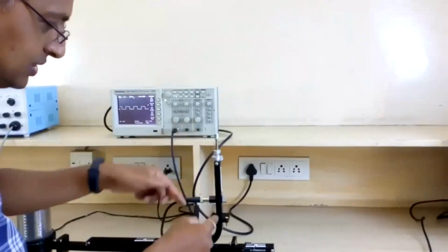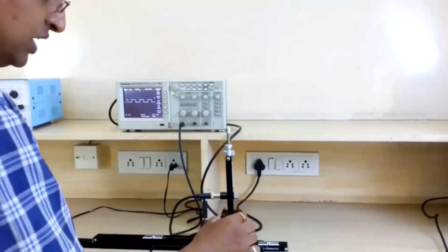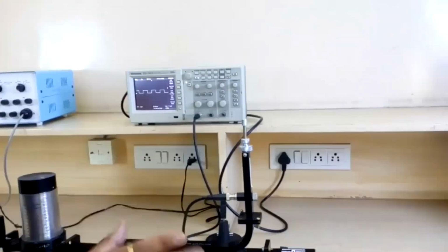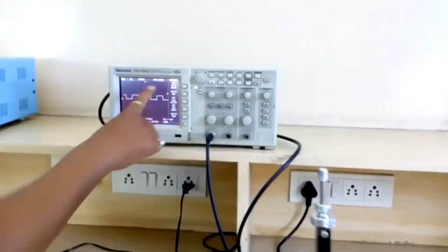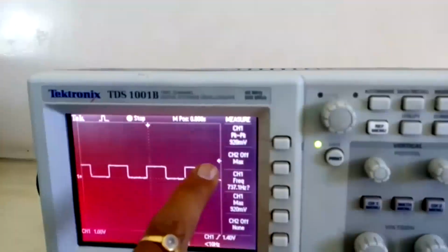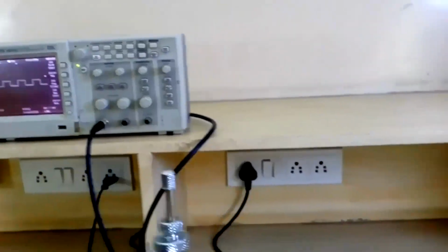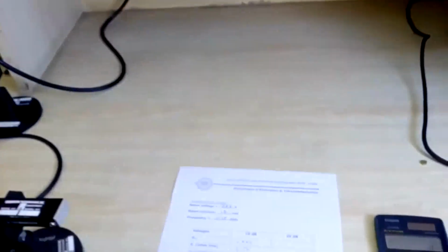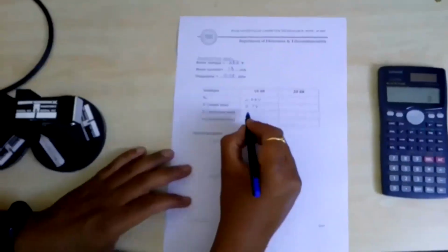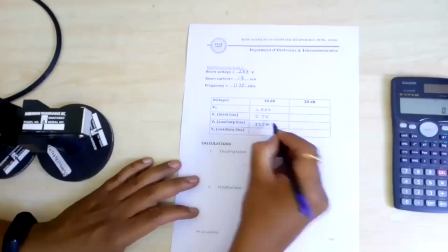The diode detector is connected to port 3, which will give me VF, the coupled power. You can see the output connected to the CRO is 920 millivolt. So I can note down that the auxiliary line VF, or coupled voltage, is 920 millivolt.